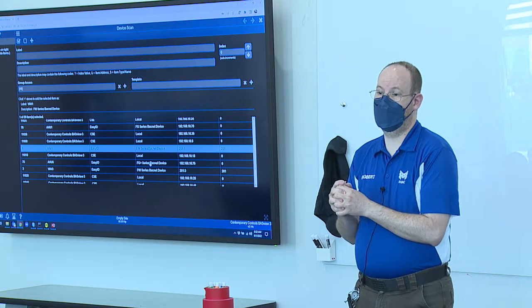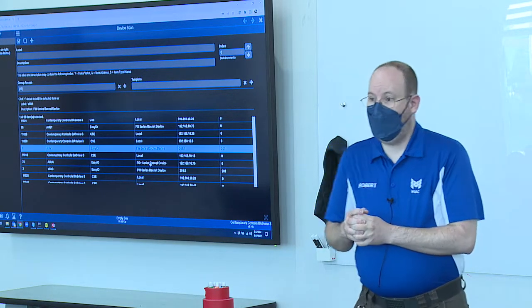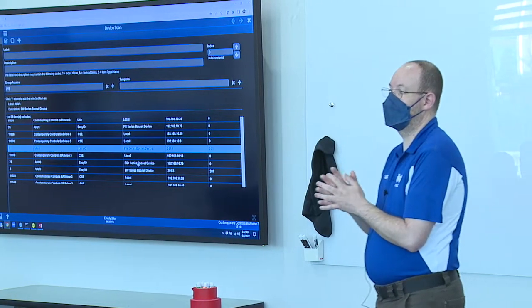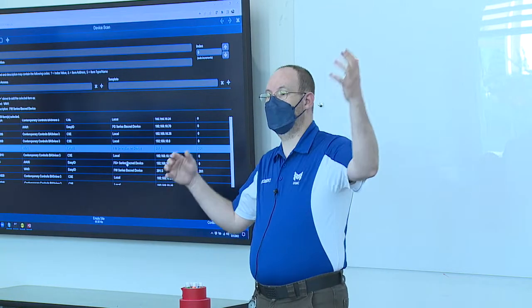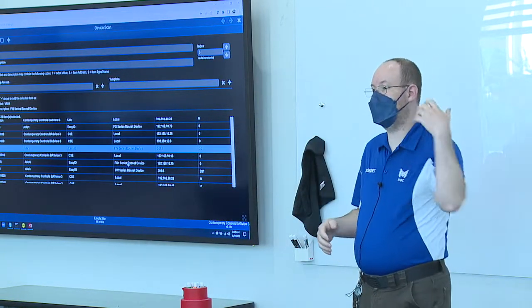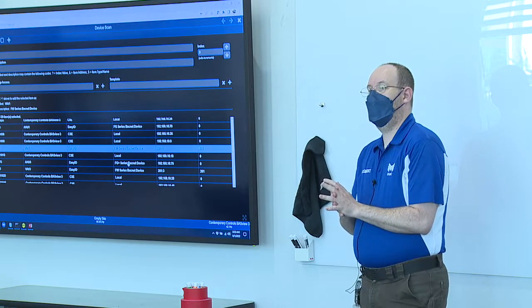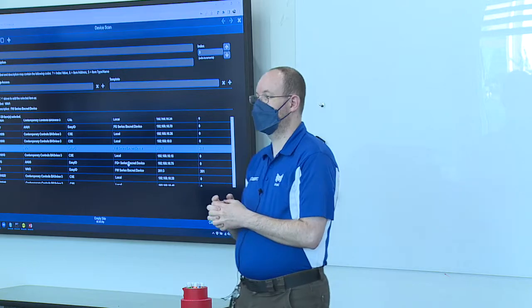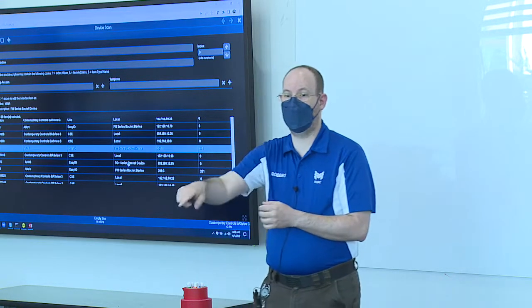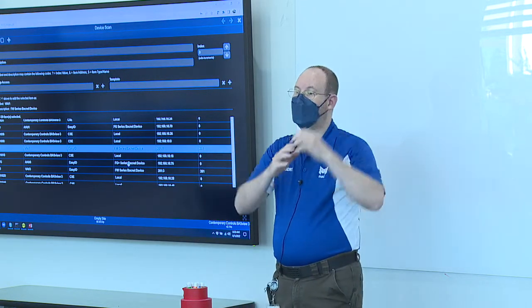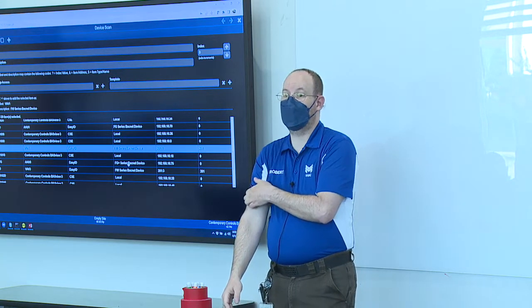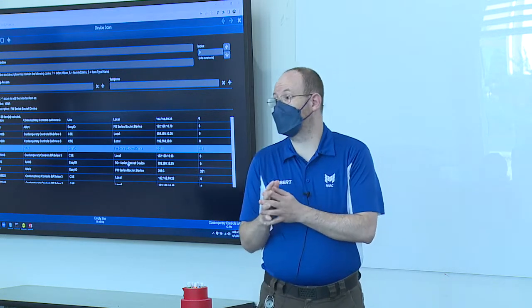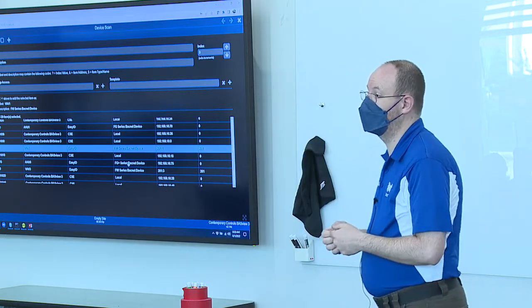Really kind of depends. Now, how many people in here have used a BACnet discovery tool before? Show of hands. Niagara, Johnson, ALC, EasyIO. How similar is this to what theirs looks like? Pretty similar. You click the button, tell it to scan, and wait for it to give you results. That is pretty much how these work. It's pretty easy. That's one of the nice things about BACnet.